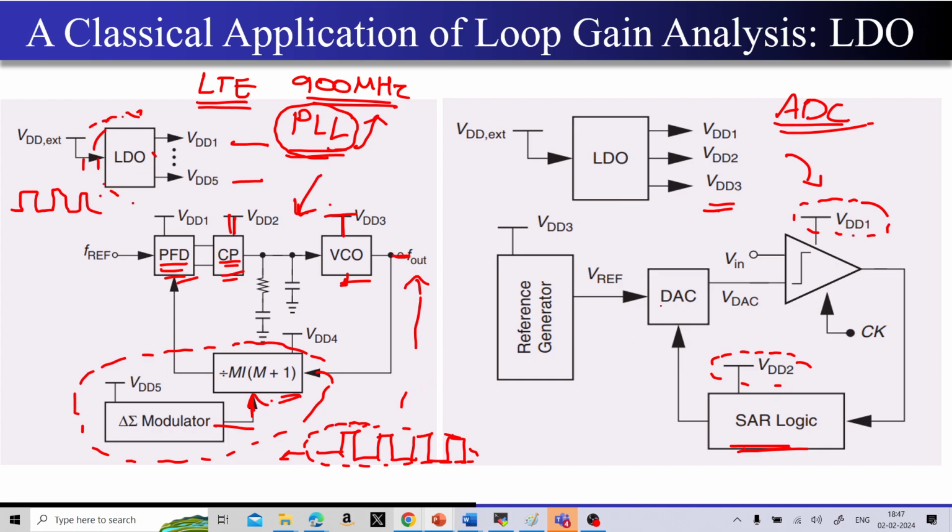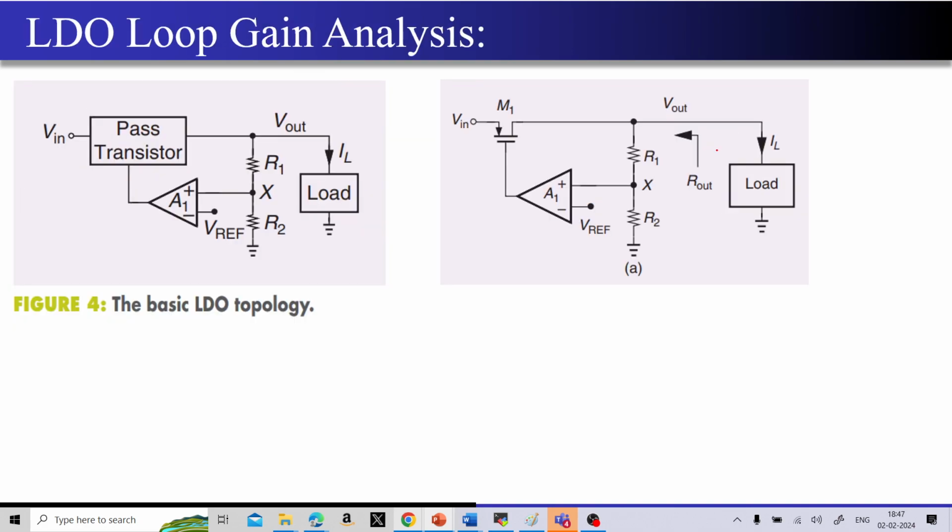So now what we need to do is have one LDO that will give me a very clean supply. Now if you look at the internal architecture of the LDO, first of all, whatever we did the last time, let's check whether this feedback that you are seeing over here is negative or not. If you go into the circuit details, let's first check whether this is a negative feedback system or not. Now what I will be doing is increasing the disturbance over here. I am giving the input at the gate and taking the output from the drain.